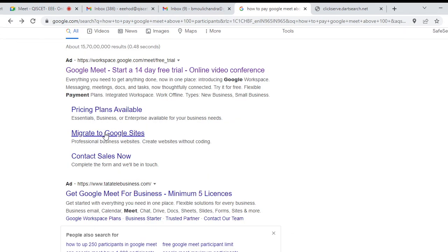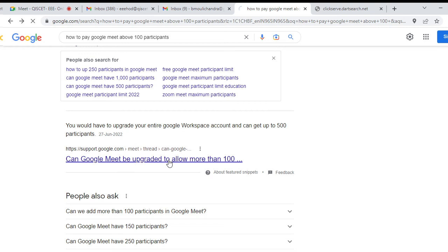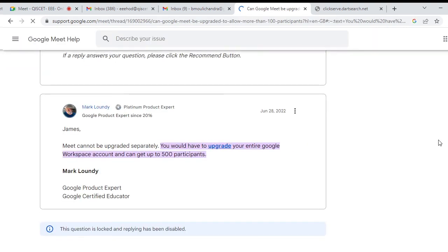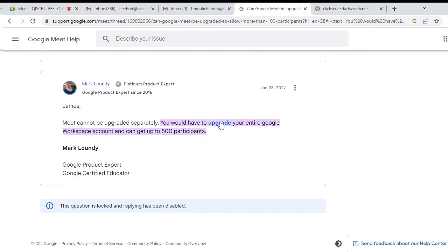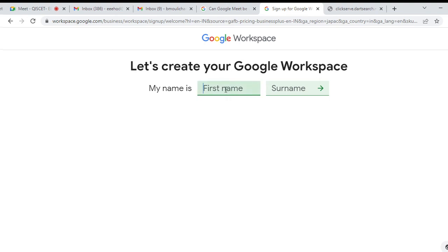For this small network only, a lot of configurations are there. I think here there are 2^15 minus 1 configurations, a very huge number for such an 8 bus network itself. But in a practical system you may have 1,000 buses and lakhs of feeder lines. Now how to configure it and how to check its stability is the main concern in our study. We cannot do it manually very easily.